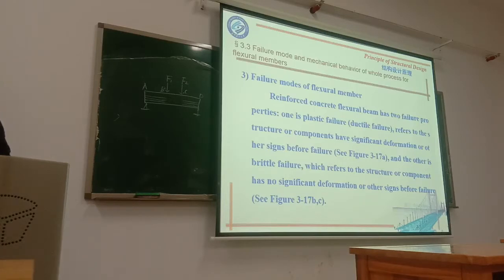So, what's the meaning of these things? Have any idea? We told before. Plastic is... once you put too much steel or too little reinforcement in the beam, it's not good. So only if you design the beam according to your calculation and put suitable, reasonable reinforcement inside. Otherwise, the failure mode is totally different. So the first is plastic failure.